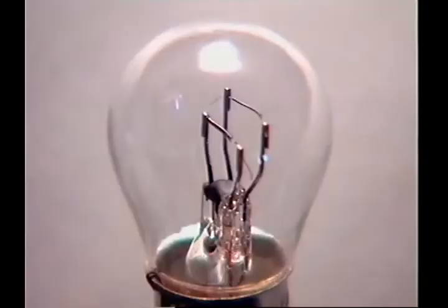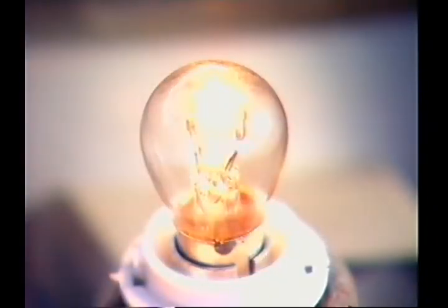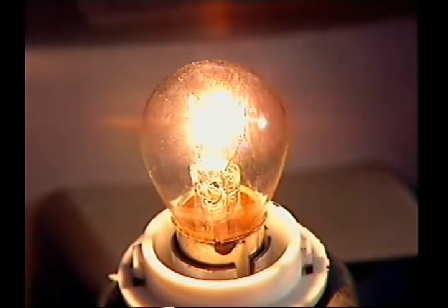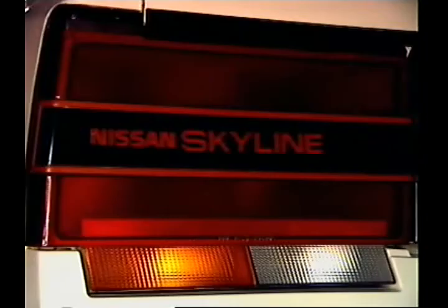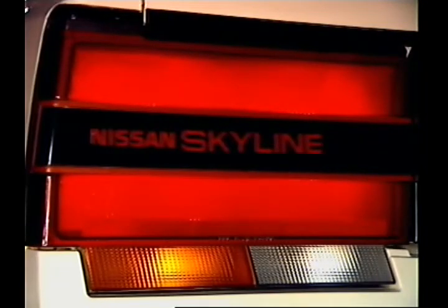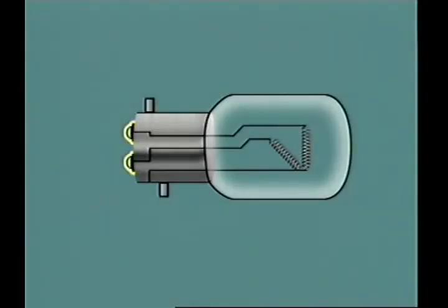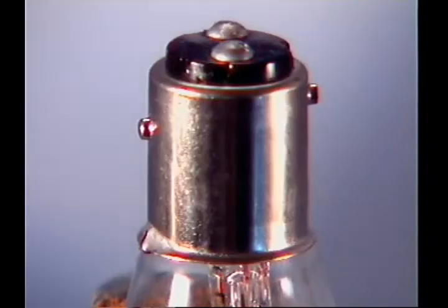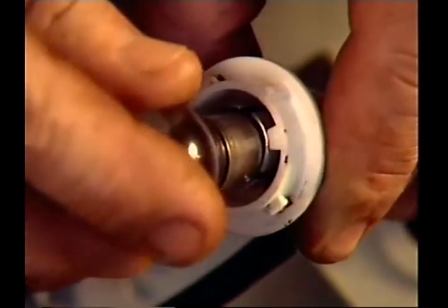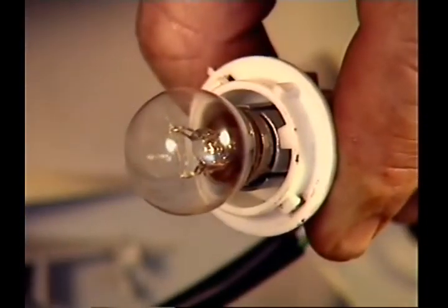The bayonet pins on the cap are used to lock the bulb in position against the spring-loaded terminal in the socket. Some bayonet-type bulbs have two separate filaments in the one envelope. Each filament has a different light output and is operated by separate circuits, usually in a stoplight-tail light combination. Two lead contacts at the base provide the input connections to each filament, and the other ends of the filaments are connected to the cap to allow the circuit through the filament to be completed. The bayonet pins are offset. This ensures that the correct filament is inserted in each circuit.